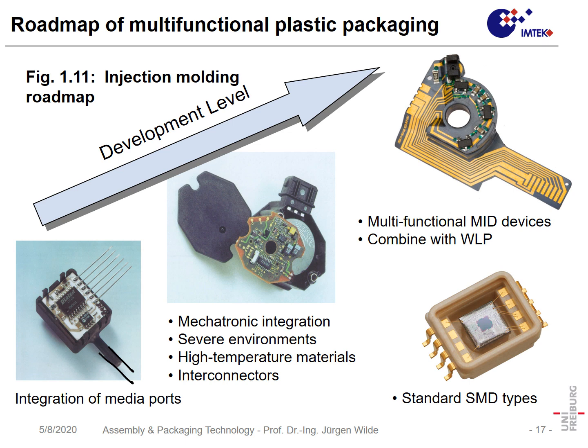On the other hand, you need electrical interconnections, and so it gives you output what the pressure is. Again, for the manifold, you need information what the position of the throttle is. That again can be done with a sensor. In that case, it's not an analog but a digital sensor. And again, here we have a combination of printed wiring board and some injection molded part, and again we have an interconnector here.